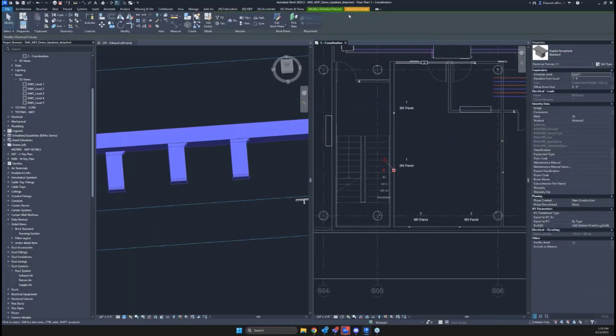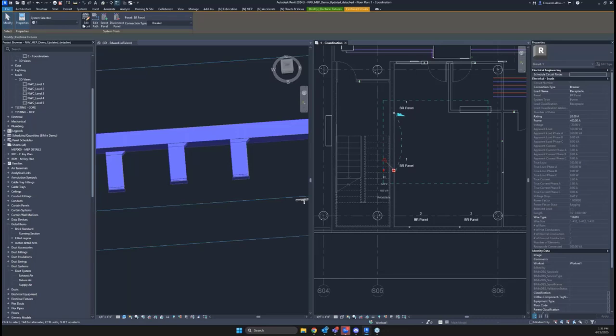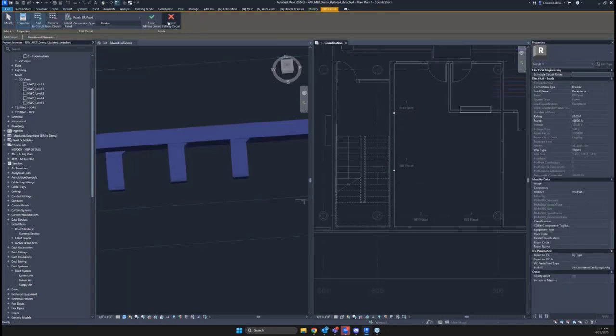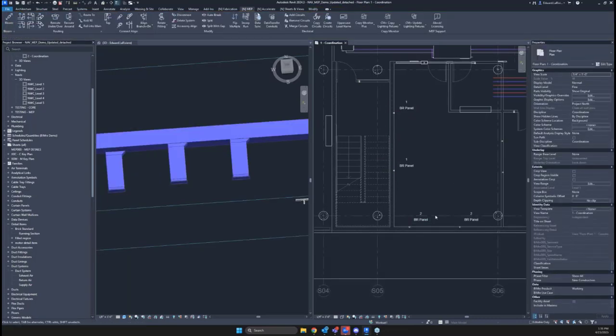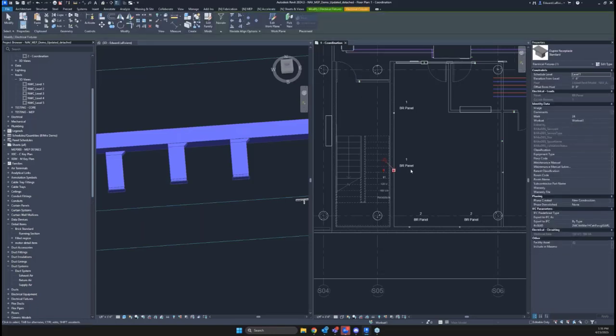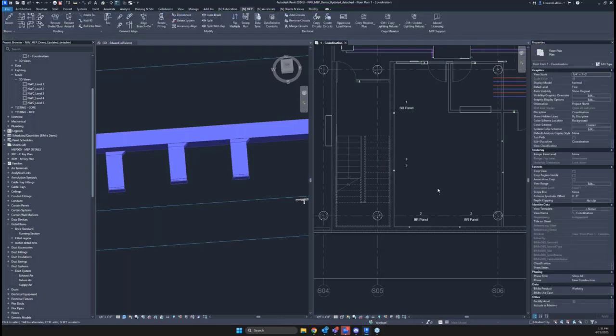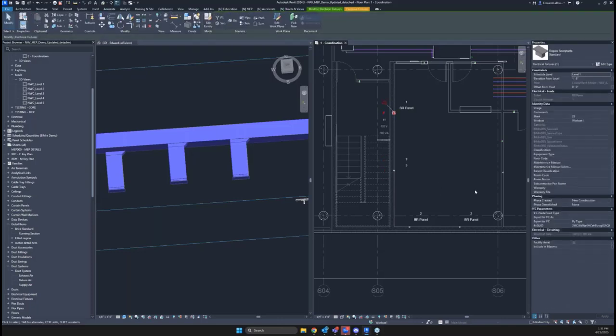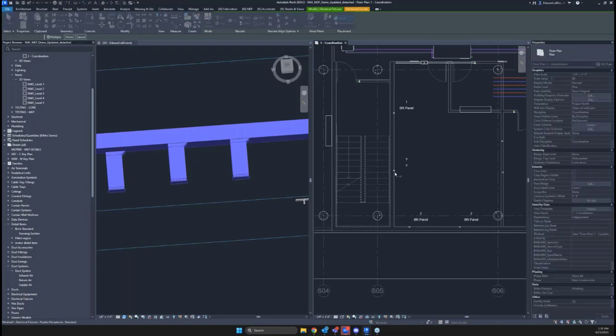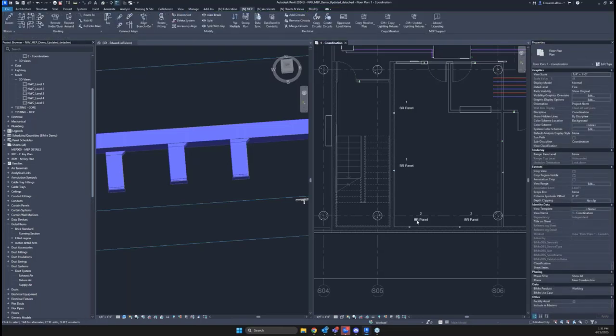I don't want to have to click every element, go to circuits, edit my circuit, remember to do everything here and actually finish it. I'd like to just sit up in this top-down view and do some quick stuff. Like if I want that to go back to being nothing, I can use a circuit remove, and now it's back to nothing. If I want to add it back to circuit 1, circuit add, choose your element, finish. Now it's part of circuit 1.